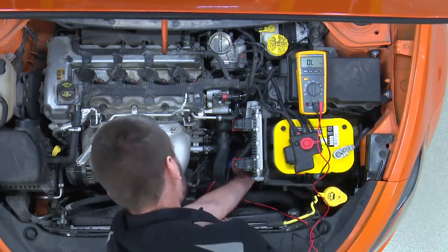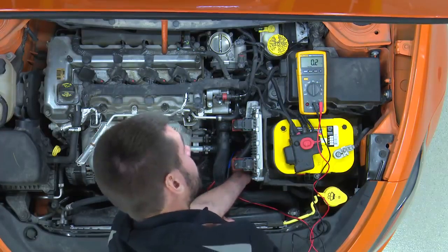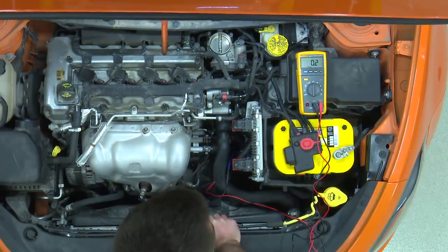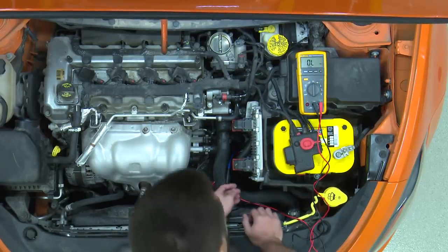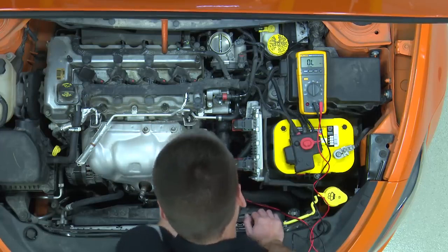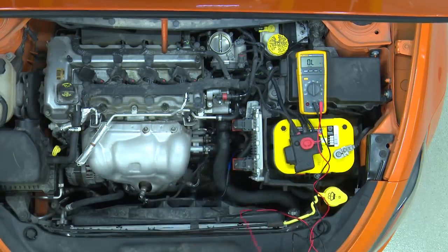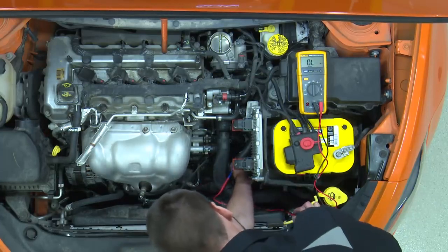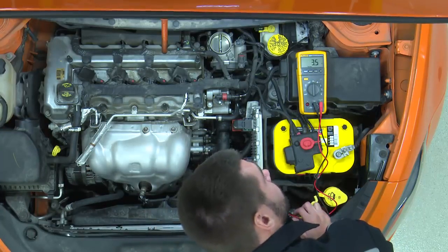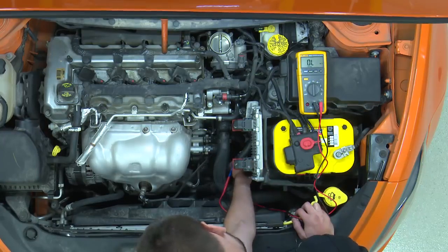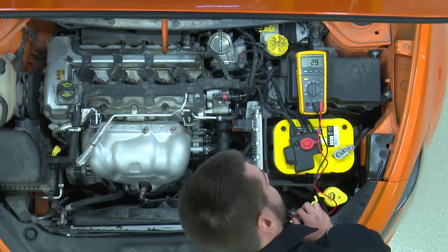All right, let's go to reverse now. Can you shift it into reverse? Yes, key on. And we should see our signal, perfect. Our signal goes open because our range switch is no longer in park. So I'm going to grab another lead here and hope that I have the right pin for reverse. Hey, look at that. That was pretty good odds. I had a 1 in 6 shot that I was grabbing reverse. And all right, there's reverse.